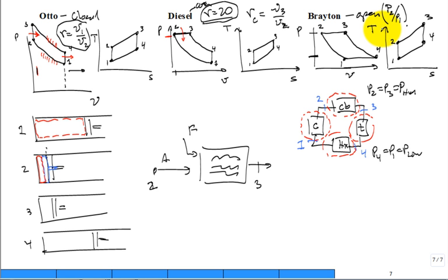They try to push it up even into the low 20s because that is great for performance. But it's really hard to do a good job of designing and building and getting to run reliably for a long time a centrifugal type of compressor. I think I showed you a video of the stators and rotors rotating like that in a compressor, and that's just a challenge.